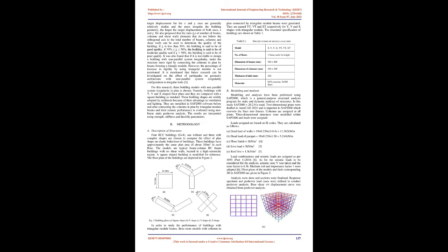He analyzed 5 rectangular models with non-parallel system irregularity and discovered that for regular buildings, the target displacement for the X and Y axes are generally relatively similar, and the more irregular the building geometry, the larger the target displacement of both axes, X and Y.